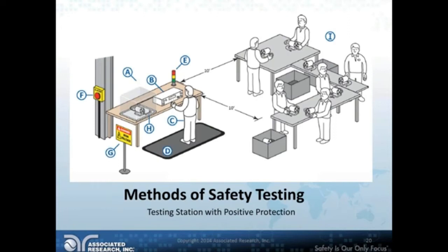That ensures, number one, that the operator can't touch the DUT while it's testing, and number two, should somebody accidentally bump an enclosure door or open it up to where there could be a live exposed conductor or a live DUT while there's a high pot test happening, the high pot test immediately stops and automatically discharges the unit under test. A couple other things of note in here.